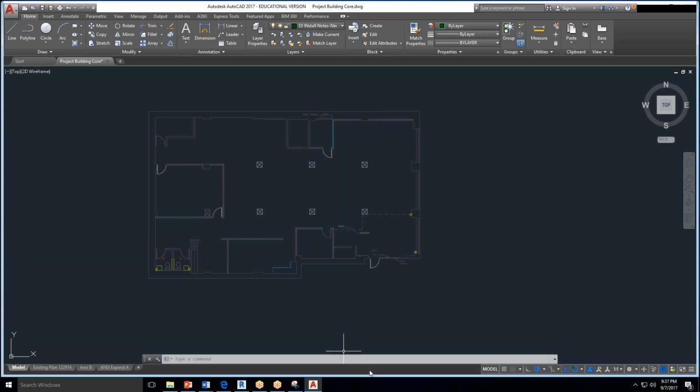So level 1 would be the 10-foot wall and everything on the first level. Level 2, if I'm putting a roof on, is the roof. So you want to put it on level 2, because it means the bottom of the next level up, which is where you want the roof to be, because that's the top of the first floor, if that makes sense.